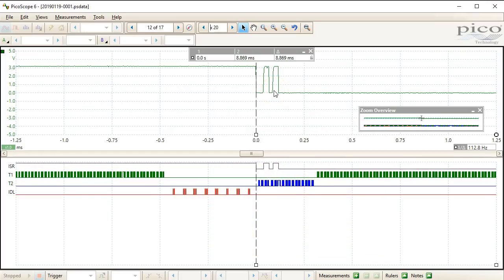Specifically, in this particular situation you see 3 falling edges in the ISR line, which means that the semaphore was signaled 3 times from the GPIO interrupt. However, the Blinky2 thread went only 2 times around its while(1) loop. So let's find out why.